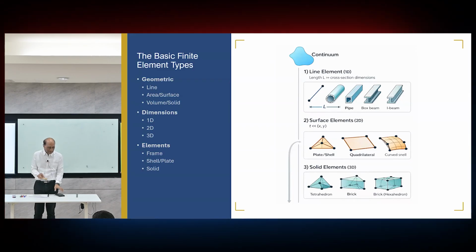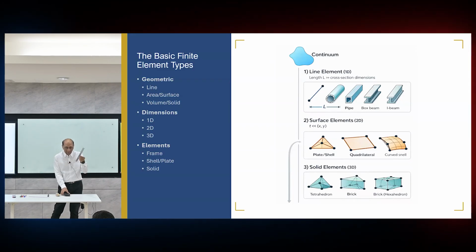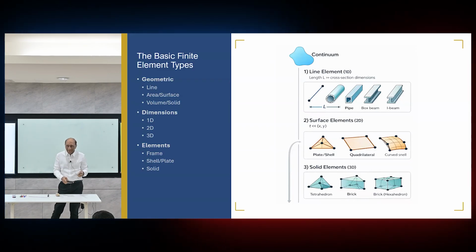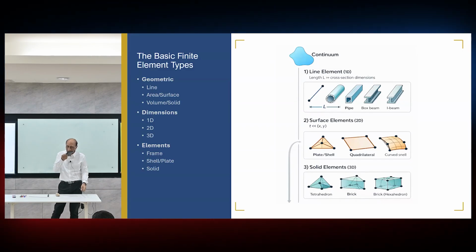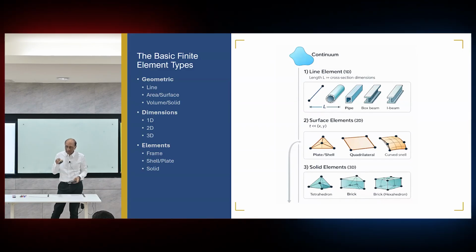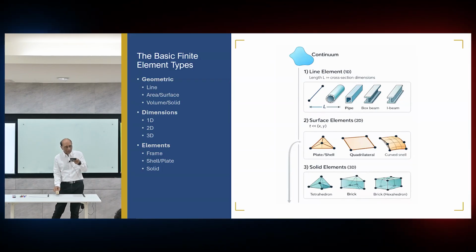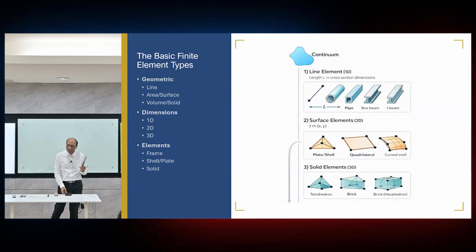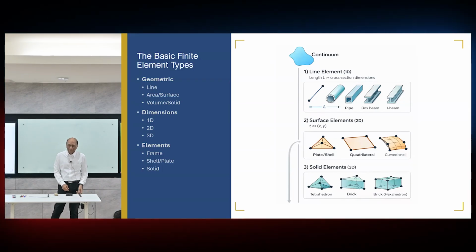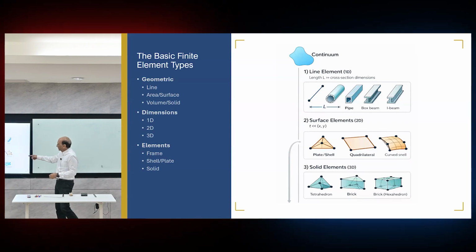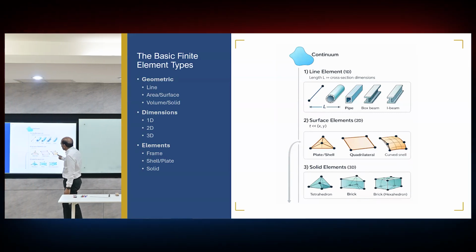So you can see these three things are three different thickness ratios, right? Is this plate or shell? What about this one? And what about this one? So we just say, oh, this one is now solid because it's very thick. This one, I don't know, still plate or shell. This, I'm sure it's shell, right? That's how we make decisions. So that's the plate shell elements.